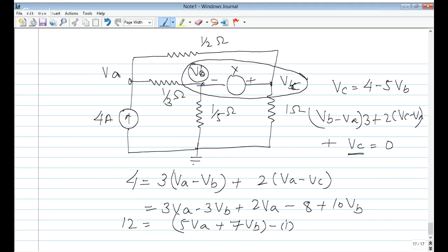So next is from Naveen Kumar. Compared to a two winding transformer, an auto transformer has less copper losses, because the copper requirement is reduced in the case of an auto transformer. Leakage reactance is also less because the two windings are wound on the same core, so it is also reduced.